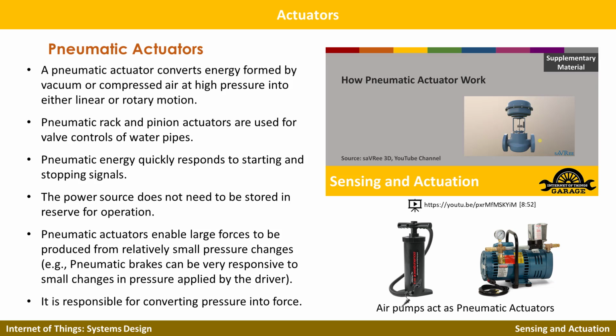drainage systems. It is worth highlighting that pneumatic energy quickly responds to starting and stopping signals. So you can quickly stop or start. This is easier when we are using IoT to control, because you know that as soon as the signal is received, it will stop or start. This is not the case for hydraulic actuators. It takes some time, so you need to pre-calculate when to stop and start the motors which use hydraulic actuators.